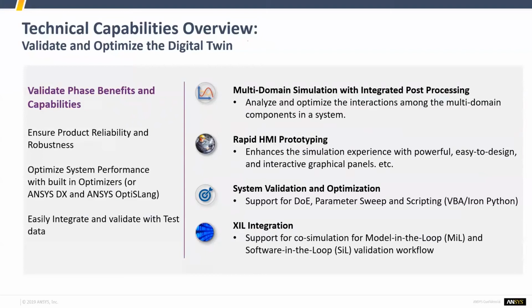And finally, we have system validation and optimization that allows parameter sweeps and design of experiments, and we also have scripting language support. That means you can automate these optimizations using VBA or IronPython scripts. As I said before, we allow SIL integration, that means model in the loop and software in the loop validation workflows. In addition to that, we also support external optimizers, for example, Ansys DX and Ansys optiSLang.